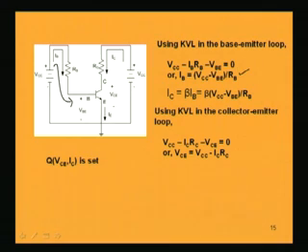This is the base current in this DC circuit, which is set by RB. Others are constant, mind you. VCC is constant, because we are applying a particular reverse biasing voltage, as well as particular resistances RC and RB. For that particular RB, IB is set, because VBE is 0.7 volt for silicon, it is constant. Corresponding to this base current, the DC collector current which flows is beta times IB. So, I can write this expression as beta into VCC minus VBE by RB.